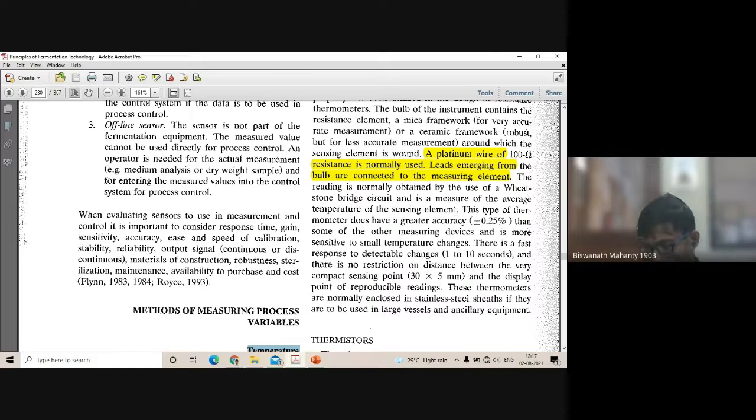Essentially we are putting a voltage input into the probe, and it is going to measure the change in volt across the element. So basically we can measure the change in temperature by this process. The same thing also happens here. For example, they take some platinum wire and measure the resistance. The wire resistance will change, so as the temperature changes, the resistance changes.